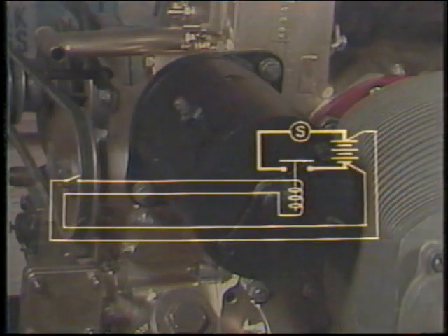By using a relay or solenoid, only the circuit from the battery to the starter need be of heavy gauge wire. The circuit from the starter switch in the cockpit to the relay near the starter may be much smaller, since the only electrical load in this circuit is a small electromagnet.